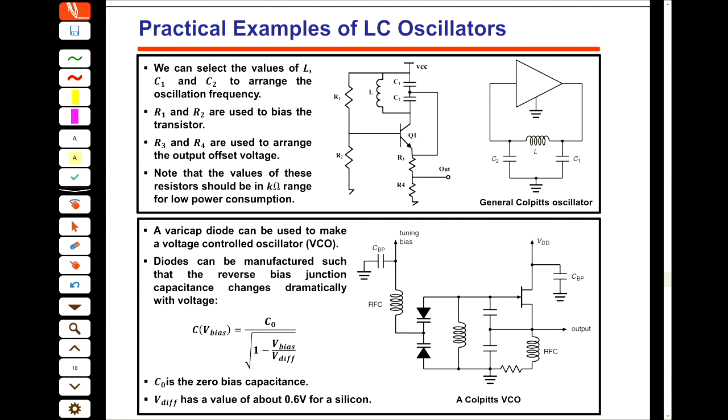This is the whole circuit that we have for an oscillator. So for your design project, you need to design a local oscillator to feed your receiver. So this is something that you have to design. You need to bias the transistor with these two, mainly with these two, and make a VBE such that this transistor is on.